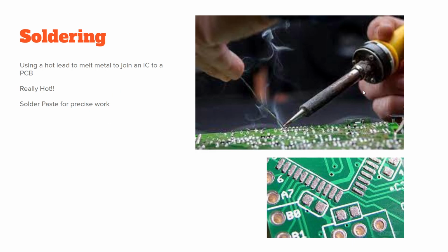The lead will get very hot. Leads often get up to 700-800 degrees. I think the ones in our labs get up to like 700 degrees. So please don't touch it with your hand. Please tie your hair back. Don't wear baggy sleeves, because it is dangerous. Solder filler often takes about 300 degrees to melt, which is more than enough to burn you, more than enough to hurt you.